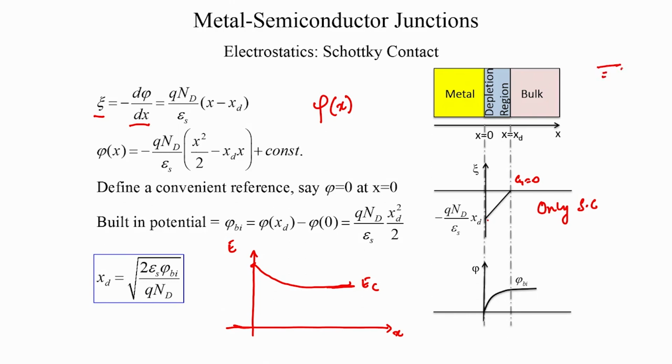So, we need to have a reference potential and then measure the different locations in x. So, phi at x1, phi at x2, etc., is all measured with respect to that reference. We will set that reference at this point. We will say that at x equal to 0 my potential is 0. That is my ground, if you want to think of it that way, my measurement ground.